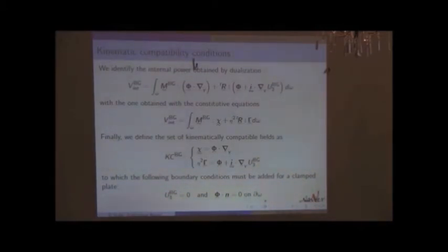It means that my plate is deformed that way, and the normal fiber rotates by itself with its own freedom, and this is minus phi alpha, this is U3 alpha, and this is gamma alpha. Alright? So the difference between the inclination of the normal fiber and the actual slope. So this is just the generalization of this idea.